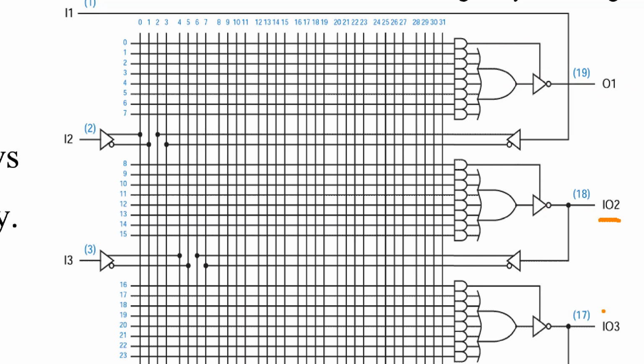For IO2, IO3 also, if you want to use this as an output, the enable signal at this must be 1. Then the output from this OR gate will go to this output terminal. Anyway, if you want to use this terminal as an input, you must disable this by applying 0.